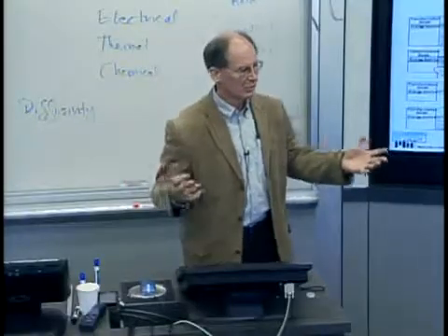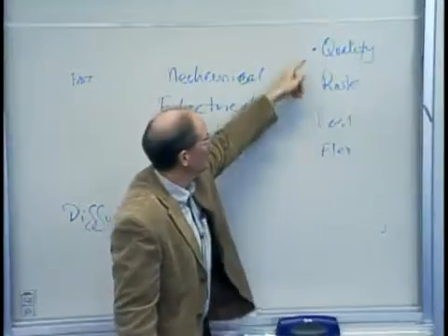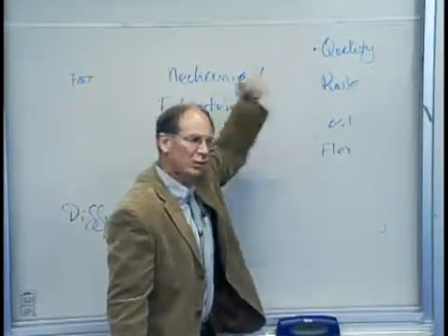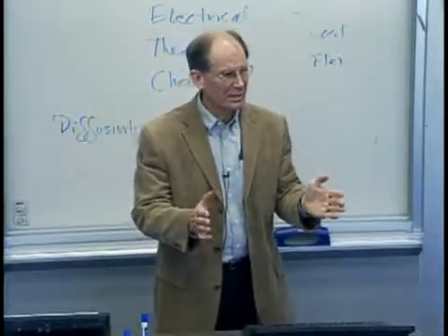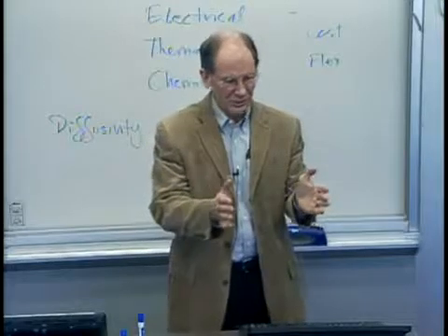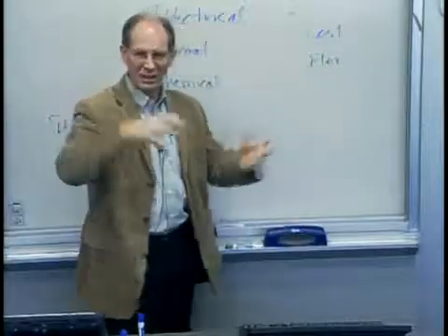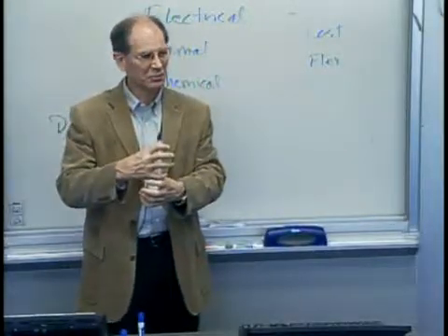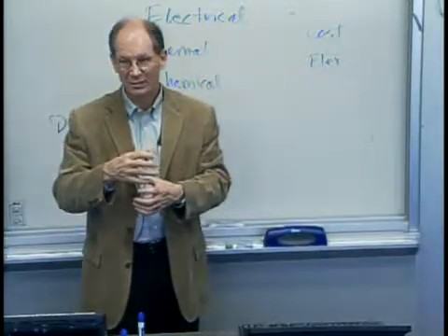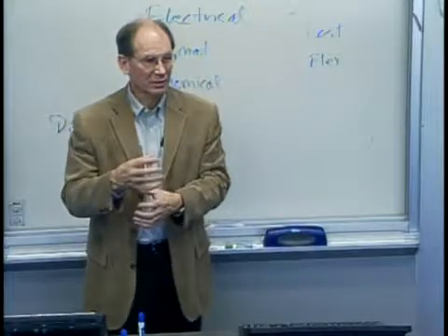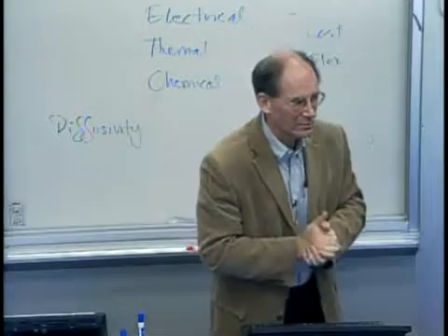So clearly this serial process is much more flexible. Really great. And I probably can control the quality better, because if it's not quite right, I just change the program a little bit. If the last one I made was a little bit too wide, I can reprogram the geometry and bring it in a little bit, and it just does it. Whereas if I'm doing the hot isostatic pressing, I've got this big expensive tool and it's not quite right, and I can't heat it and cool it like I did with the rolls on the aluminum, I'm kind of stuck with it. So why would anybody do HIP when you've got 3D printing?